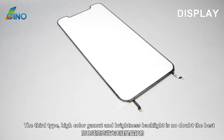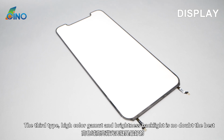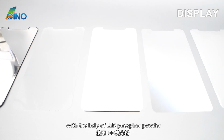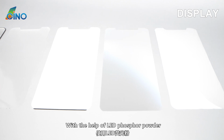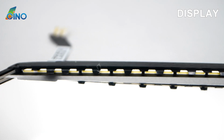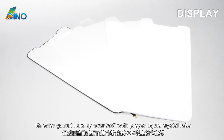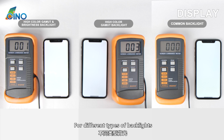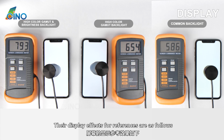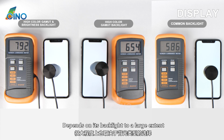Among them, the third type, high color gamut and brightness backlight, is no doubt the best. It adopts the latest COB package technology. With the help of LED phosphor powder, this kind of backlight has successfully achieved high brightness. Its color gamut runs up over 95% with proper liquid crystal ratio. For different types of backlights, their display effects for reference are as follows. So the quality of a display depends on its backlight to a large extent.